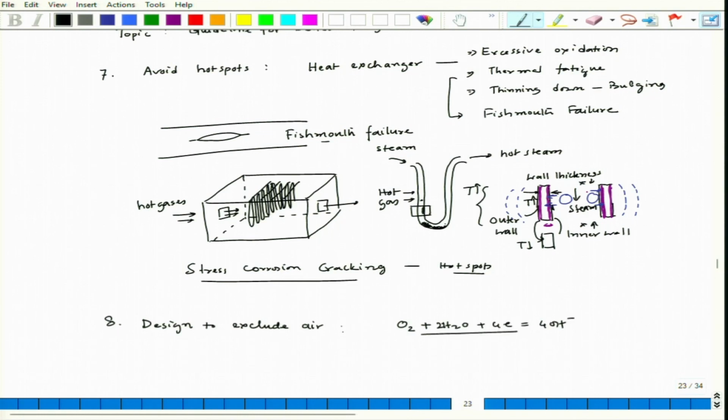So, once there is a strong cathodic reaction, and if there is moisture, then definitely the metallic component, let us say iron, can go into a corrosion mode. Okay. So, the corrosion of iron can happen. If you take care of it, you remove air. So, you are reducing the partial pressure of oxygen, and you can avoid the corrosion effect.